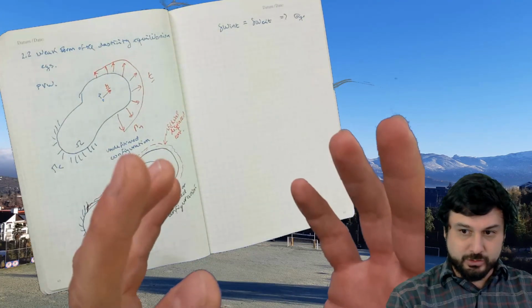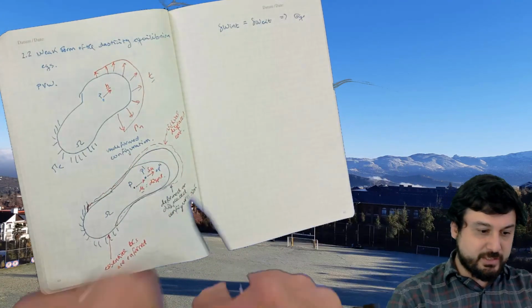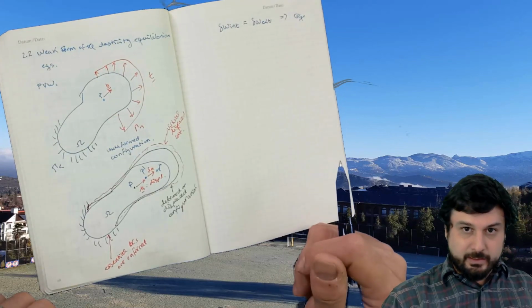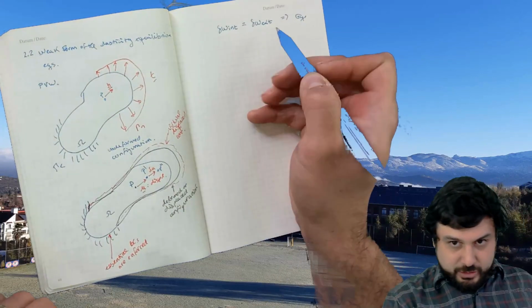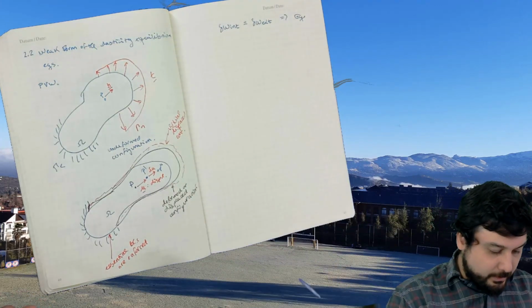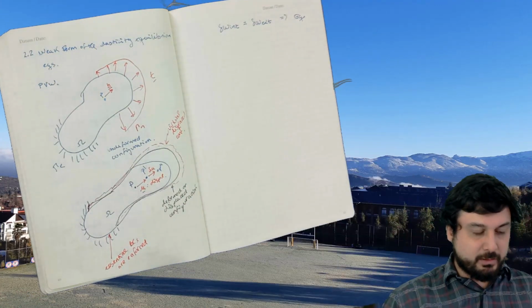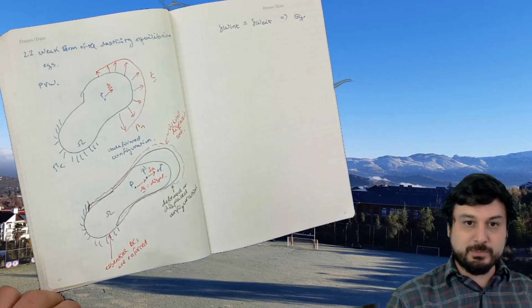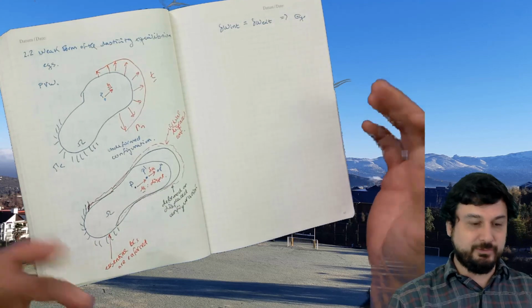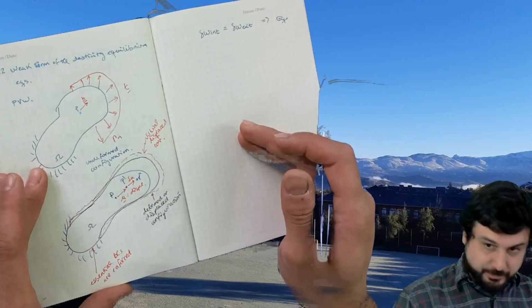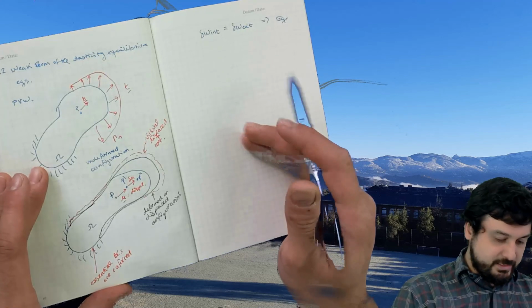The previous one holds for all points in space, the gradient is equal to the boundary forces. In this case, the internal work is equal to the external force work for all possible virtual displacement fields I can think of. So it's a vast space. Okay, and this leads to the weak form.